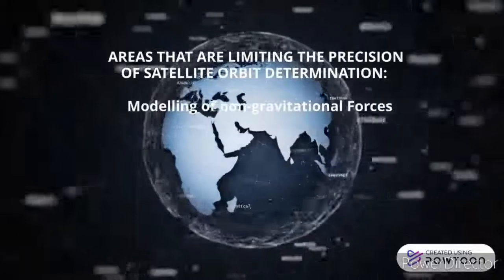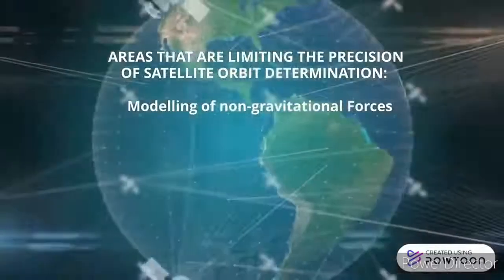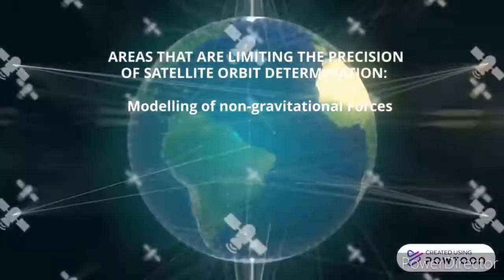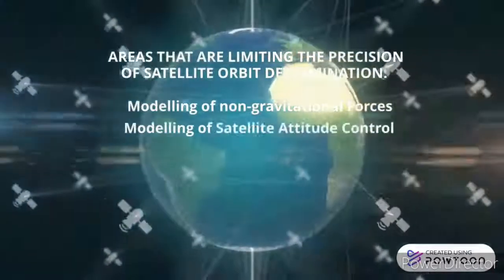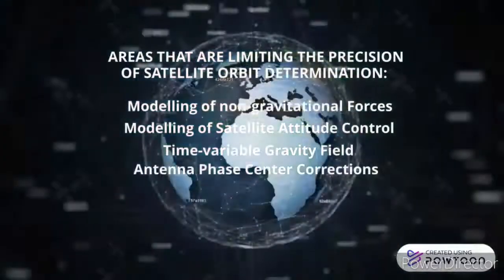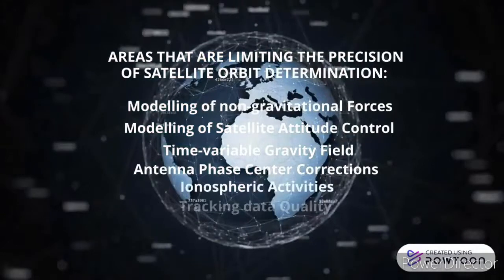Modeling of non-gravitational forces, such as solar radiation pressure, Earth radiation pressure, and antenna thrust. Modeling of satellite attitude control, time variable gravity field, antenna phase center corrections, ionospheric activities, and tracking data quality associated with clock stability.